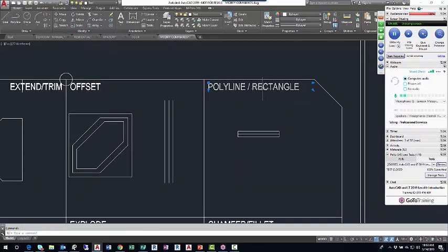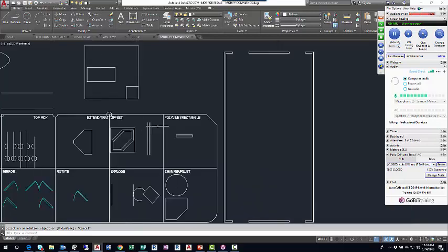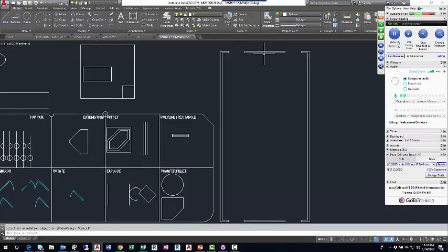It's going to tell me that. It's not giving me my tooltip, but there it is. M-text is multi-line text. If I select this and explode it, it's now single-line text, just text. I don't know why I want to do that, but some people will. They'll explode stuff. Things that can't be exploded just can't be exploded. The explode command won't hurt things that can't be exploded. So we use explode to break up the two polylines, and then use offset to create cutting edges.